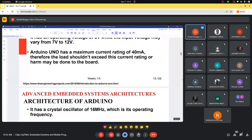So Arduino Uno has a maximum current rating of 400 milliamperes. Therefore, the load should not exceed this current rating. If you put more load than that, then you'll be able to spoil this board.